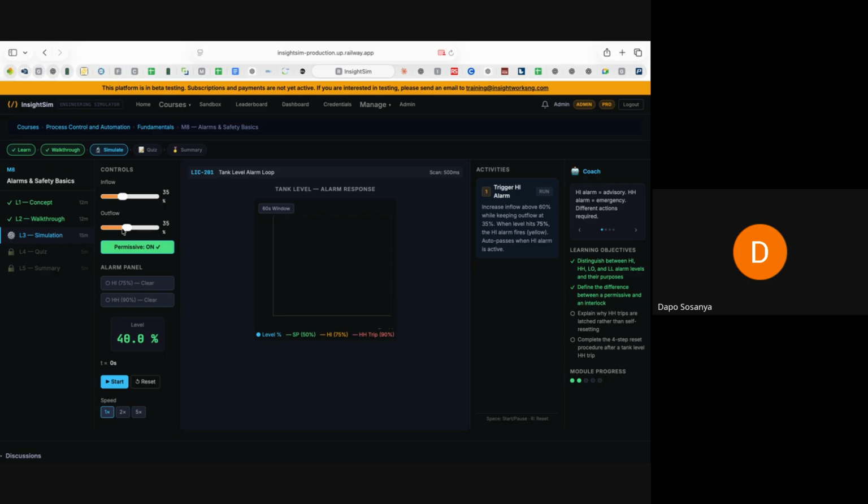You can keep an eye on the temperature depending on the fluid also, both inside and outside the tank. If temperature is critical, for example, if you have equipment with a process fluid that is sensitive to temperature, that has a very low ignition point, you want to be sure that the temperature in the environment of that fluid is way below the ignition point of the fluid itself, right?